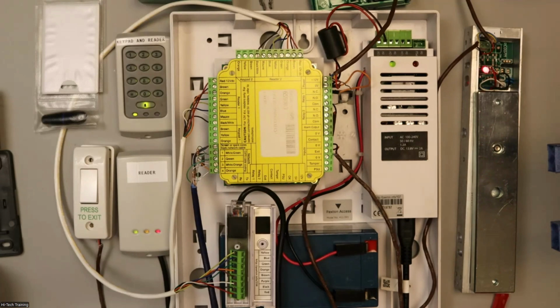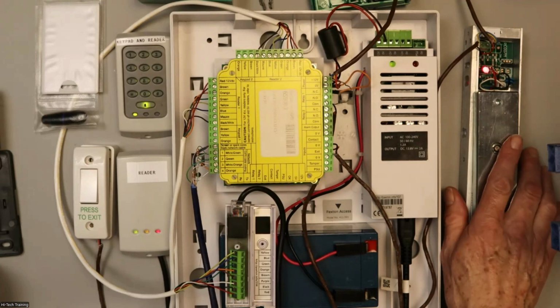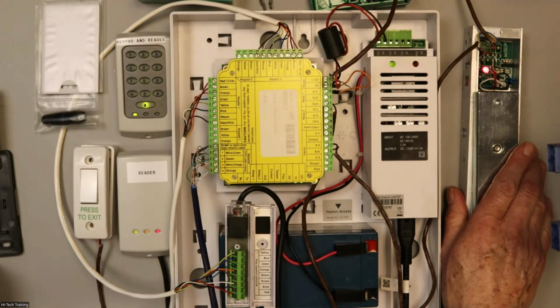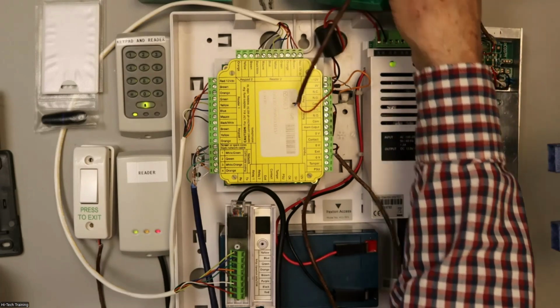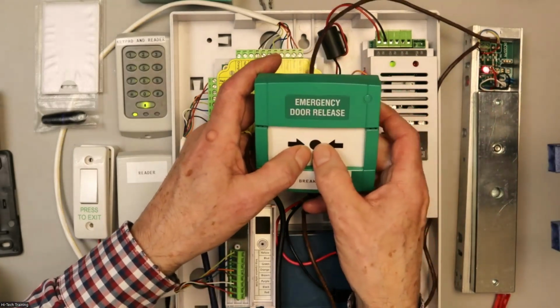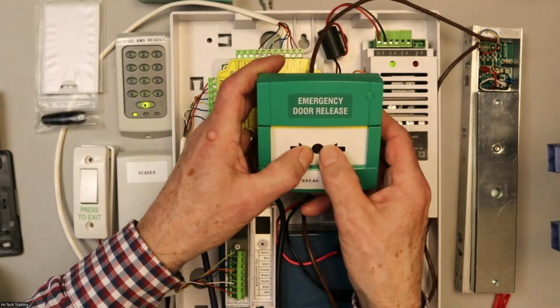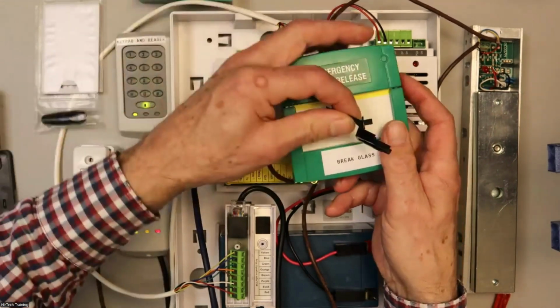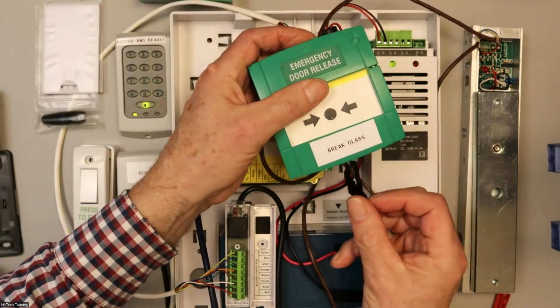Okay, so hopefully the thing is working for me. There are a few ways I can open the lock here. Well, I suppose I can press the break glass unit, which you're not going to do because you've got to reset it afterwards. Well, just reset for fun. Press there, and the lock should open. There's your lock open, right? To reset this then, I get my key, which you need to put in the right way around.